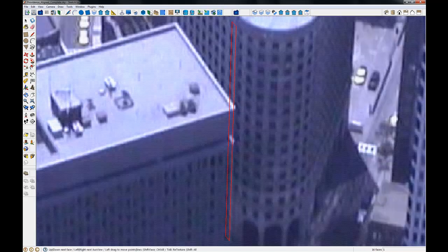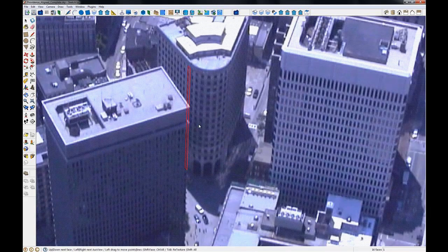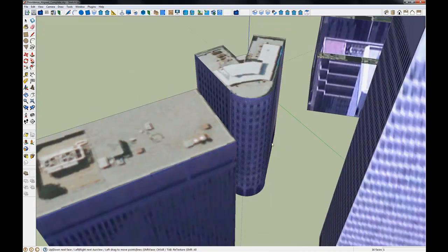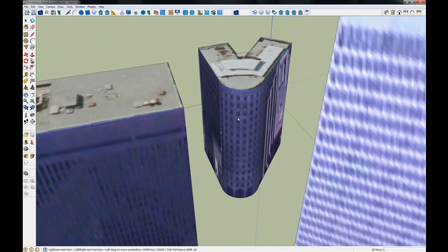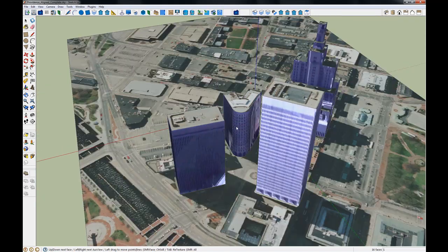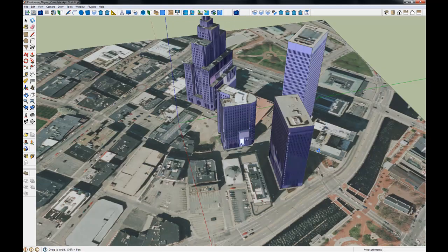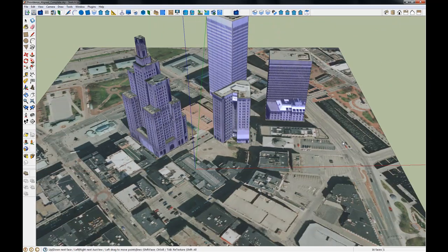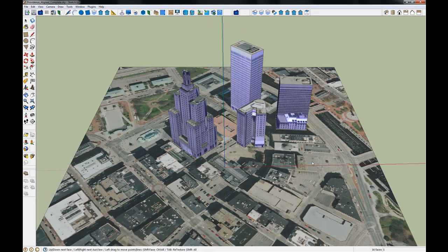Now when I click on the texture face tool, I can hold down the Control key and see all the faces are now textured from that aux view, and I can move them all at once to adjust them up here. And then I'll hold down the Control key and hit Tab to accept that. So now that curved surface has all been textured from one aux view, so you have a better contiguous texturing. So that concludes the enhancements to the texture face tool for GeoSketch 3.0.